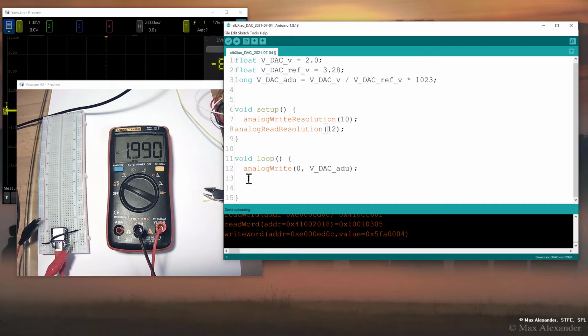Before I read a value, I want to assign it to a variable. So I'm going to introduce two more variables. These are going to be associated with the ADC. I'm going to have a value I get directly from the ADC in units of ADU, an integer, and I'm going to save that as one variable. Then I'm also going to get another variable where I convert it into voltage. I'm going to do that to illustrate and so we can see those two numbers.